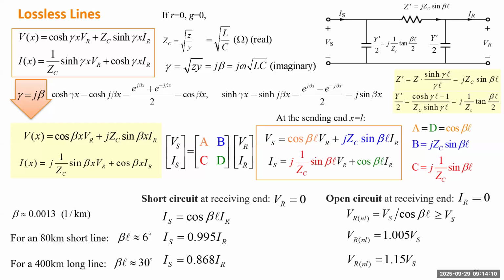So this slide is talking about the long line model, but long line model is considered as the most accurate model. It's not just applied to lines which are very long. It actually can be applied to any short line or medium line. Just for short line, medium line, we have simpler models. We don't have to utilize this model. So for instance, if the line is very short or shorter than 250 kilometer, you can